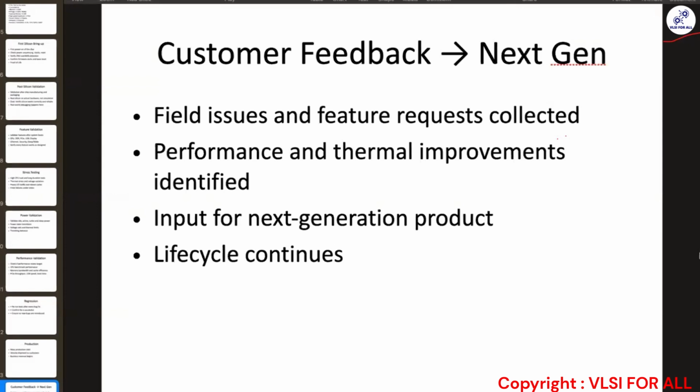Till now, before the customer, the validation and everything was happening on this side of the organization, where the silicon is built. Now the entire post silicon process, from the power on to post silicon validation, all of those things will happen in their labs. So the validation phase will start. In the validation phase, they will do the basic electrical check during the power on, then the power on phase, and then the functional validation will happen. They will check the features whichever they have incorporated.